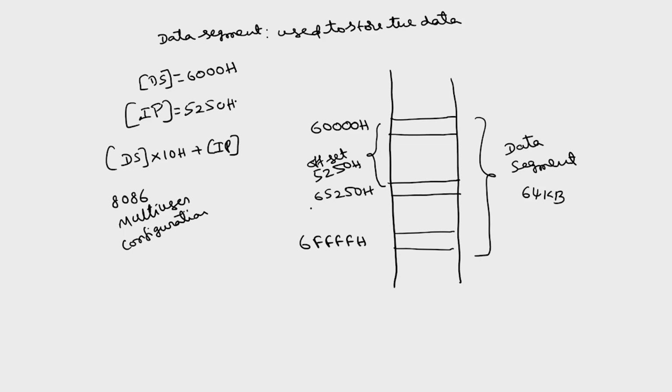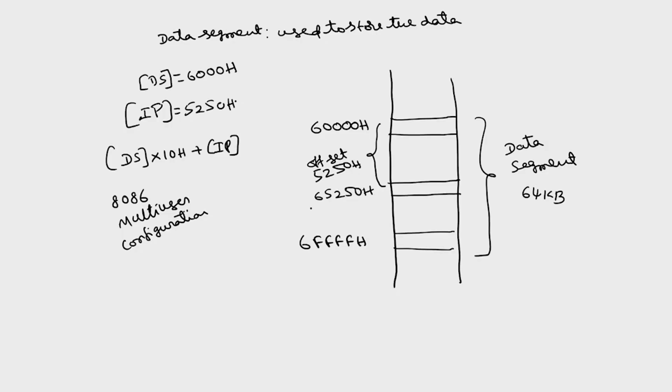8085 is only single user, only one user can program that particular 8085, whereas with 8086 we can have multiple users; more than one user can access the same 8086. So this memory segmentation enables multiple users to access it. That is another advantage of the memory segmentation. One more advantage is that, using the 16-bit address of the segments, we can access the 20-bit physical address. So these are some special features of the 8086 compared with the 8085, where segmentation is not possible.